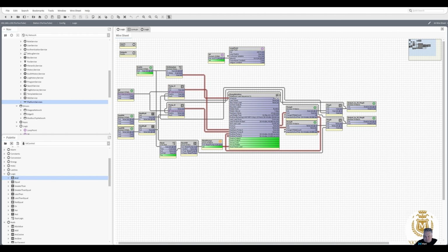I presume we could add another pump in, so we're off 3 pumps now instead of 2. That's going to get a little bit complicated on the reset bit then, because at the moment it's easy doing this because we're sending a 2 and then we're sending a 0. If we're doing a reset of a pump, adding another pump, we're going to have to send a 0, a 2 and a 3 within 3 seconds. So that's going to get a little bit complicated. I'm just wondering how I would do that, thinking while I'm talking.